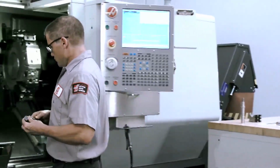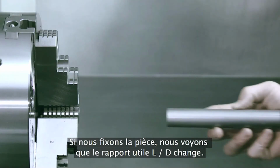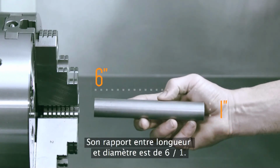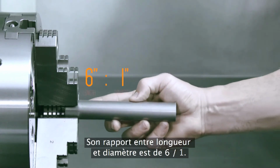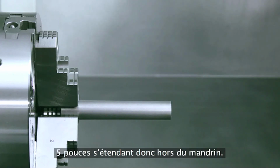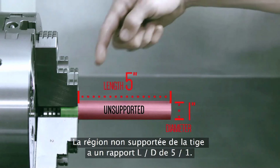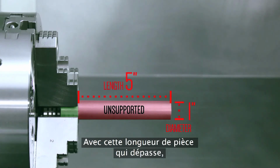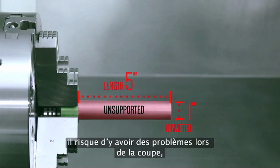When we grip the part, the effective L to D ratio changes. Here we have a 6-inch long by 1-inch diameter shaft. Its length to diameter ratio is 6:1. Now we clamp this shaft 1 inch deep with 5 inches extending outside the chuck. The unsupported region of the shaft has an L to D of 5:1. This unsupported region is what we need to consider. With this much of the workpiece hanging out, there will likely be problems cutting unless tailstock support is added.